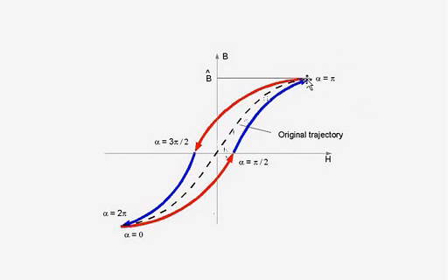I gave that to QuickField. And for core loss, I calculated it using the Steinmetz function, which I'll show a little bit later, which bases the core loss on the peak flux density in the sine wave and also the frequency. It's a power series. It's actually the peak flux density to the power 1.9.